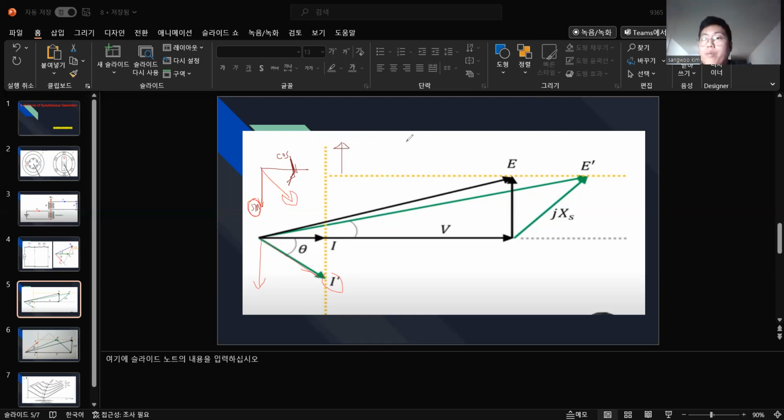So before we move to the underexcited part of the page, what happened? Look at that. E equals N F phi F, right? Phi F is IF, right? So if IF decreases, E also has to decrease. We could expect that, right? So let's see, with this expectation, what happened?